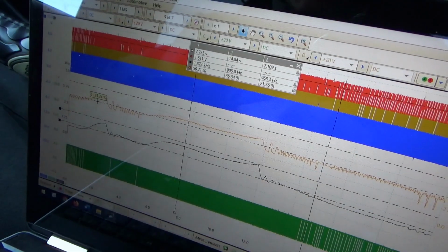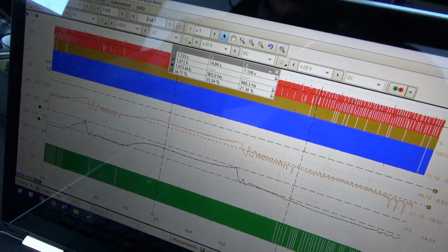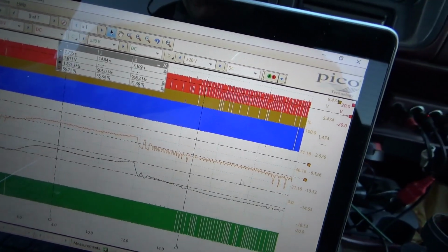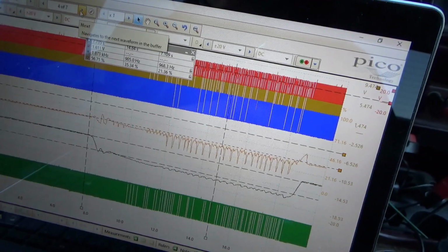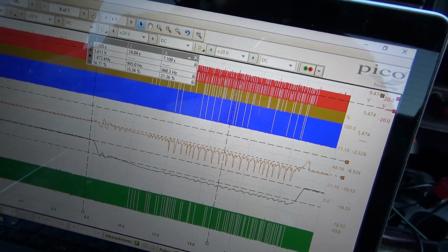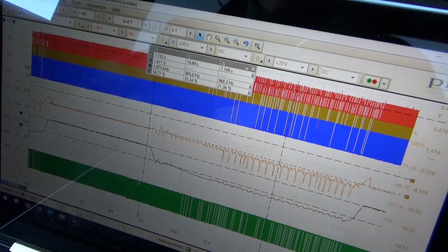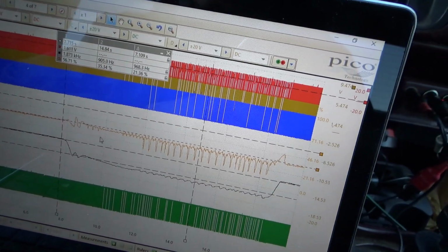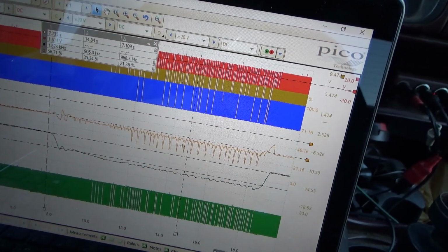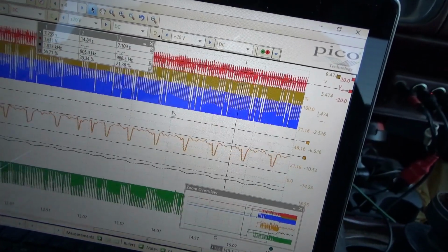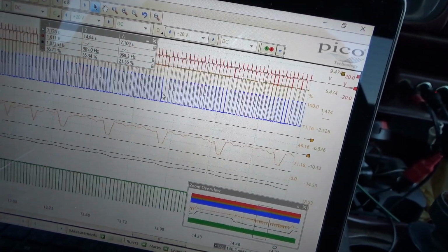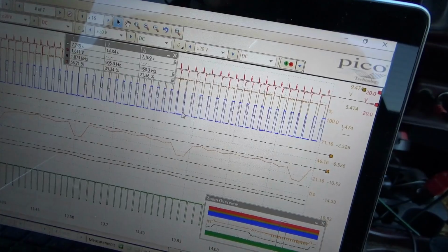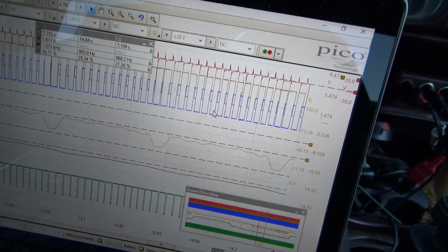Then I power brake it, nice and smooth. Lumpy, lumpy, lumpy. Power brake it some more. Put it back in park. Look at that. RPMs go up, and then we're back to 2,000 RPM. Back in gear. Look at this. Look at the duty cycle. This is why the math channel is key, because you would be looking through these pulses right here, and like, yeah, we do have a really thin pulse, a couple thin pulses, and then back to normal.